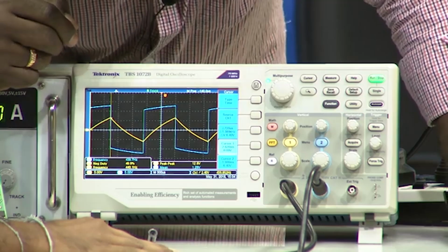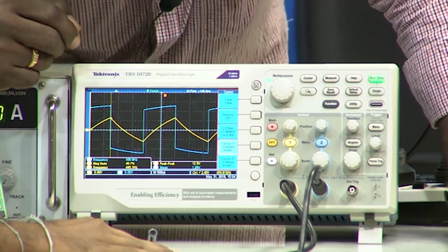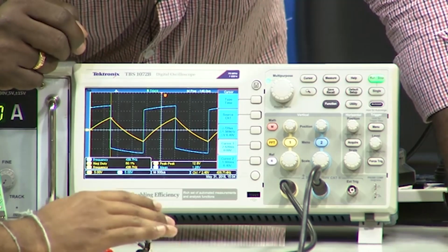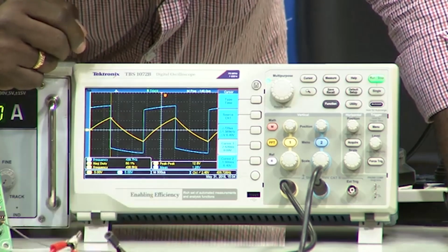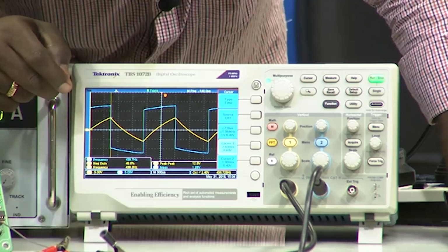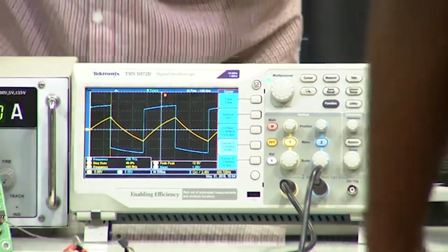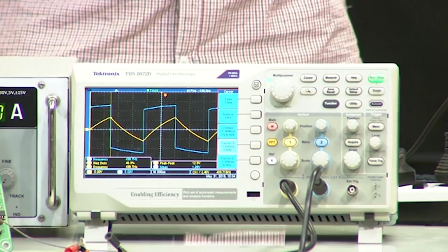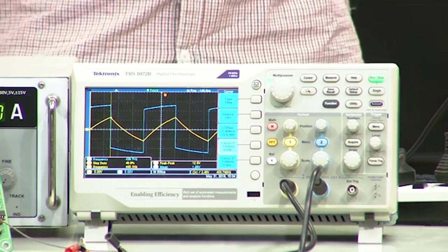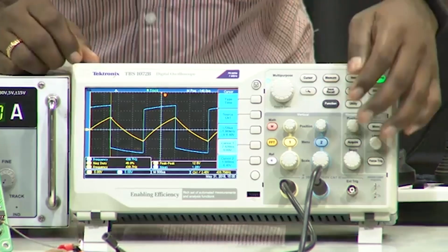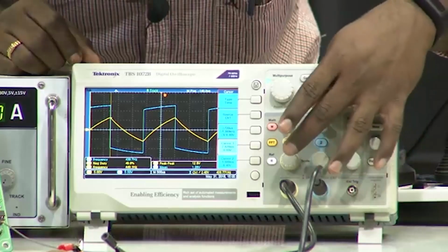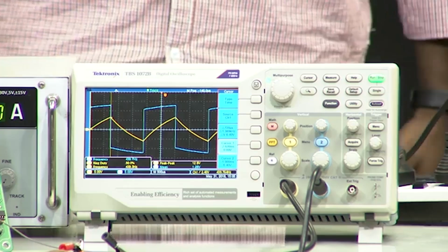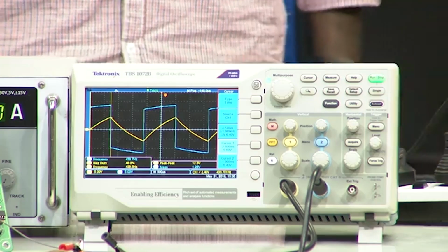The difference is because of our tolerances, probably due to the capacitance and resistances, as well as the plus VCC and minus VCC states also. We have applied plus VCC and minus VCC as 15 volts, but the op amp can only go below that particular value, and that is the reason there is a small offset variation, right. We can also see T1 and T2, but as we have already seen in the simulation, it looks the same way even in the CRO, right.